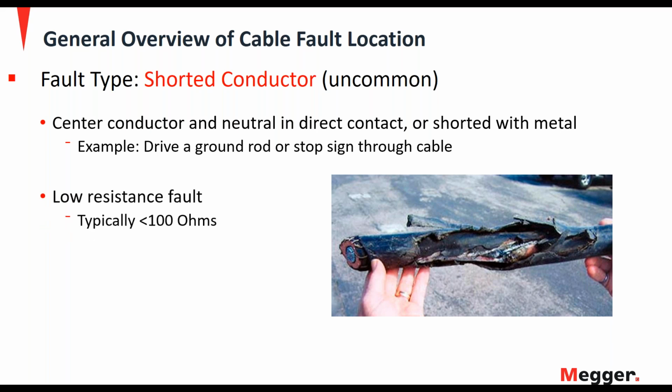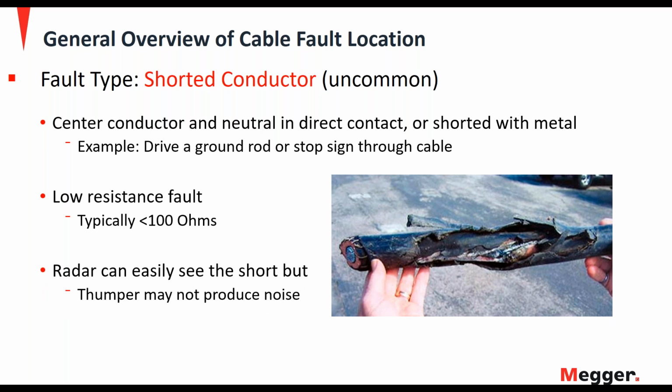If it does happen, it's a low resistance, typically less than 100 ohms. And the radar can see the short, but because there's no gap to flash across, if you connect the thumper and thump on it, it may not produce any noise to hear for pinpointing.